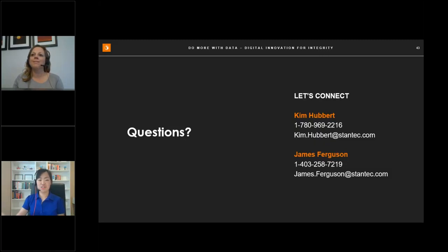Okay, thank you for the question. So when we evaluate multiple IMUs to detect the change in bending strain over years, the minimum filtering thresholds can be as low as 0.02% after those features are identified, and then those features need to be classified according to the source, the type, and the activity, by considering the elevation change detection from LiDAR data and construction or maintenance activity records.